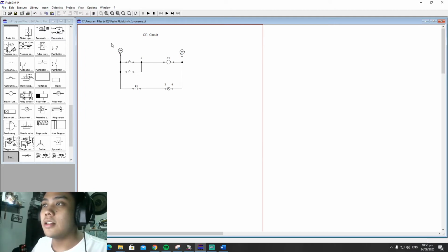A relay circuit is actually known to be a device that can handle very large loads. In a relay circuit we have a coil. This coil is actually associated to different contact switches that can be found in the relay circuit. So, for example, when the coil is being energized or when voltage is applied, the contact switches associated to that coil change state.